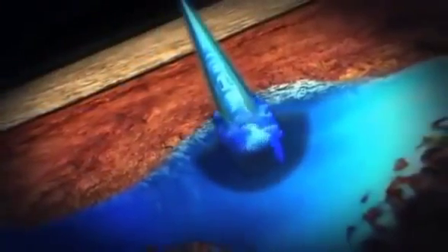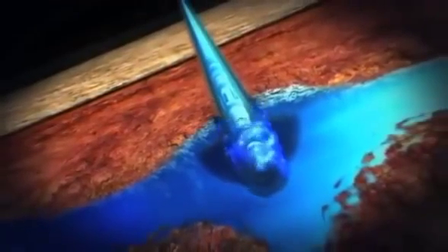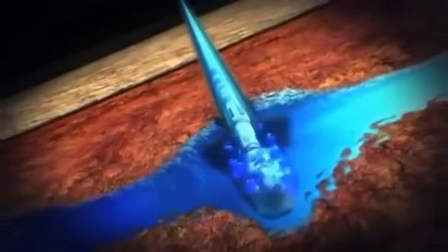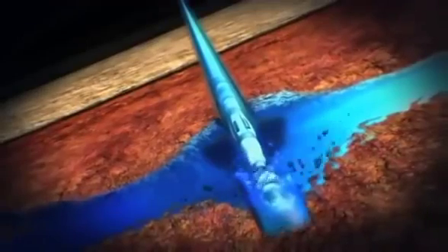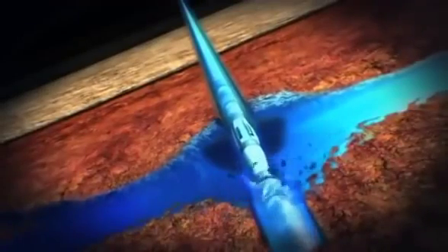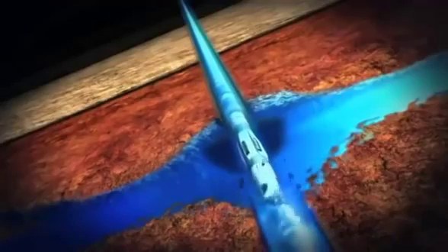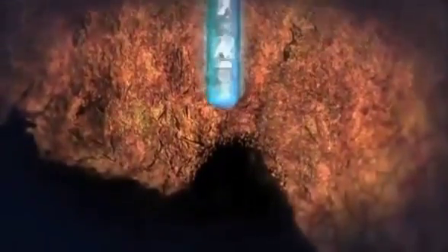To continue drilling, fresh water or brine is pumped down the drill pipe. With the annulus closed and pressure balanced, the fluid can't return up the annulus, so it finds the path of least resistance, which is the lower pressure in the first fracture. As this sacrificial fluid is injected, it carries away drilling cuttings and any produced fluids or gas. Reservoir conditions do not affect the fluid injection rate.